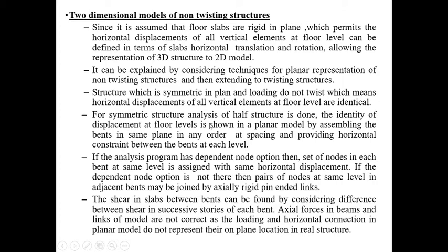Then for a symmetric structure, analysis of the half structure is done. In the same way we go for the half structure, and the identity of displacement at floor levels is shown by a planar model, which is represented by assembling the bents in the same plane, in any order of spacing, and providing the horizontal constraint.